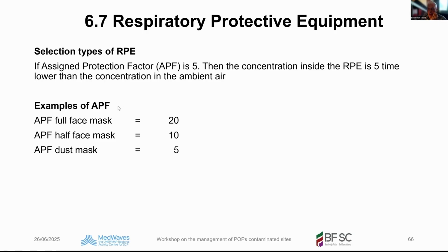When you enter your sites with small vehicles, I told you that you have to use the zoning. In the picture of the zoning, you have your decontaminated zone. So you enter through the decontaminated zone into your contaminated zone. And when you go out, you enter the decontaminated zone again, where you do the decontamination, where you clean your wheels and the outside of the vehicle. And then when it's clean, you go out. So the zoning is an important aspect of not taking contaminated parts outside your contaminated zone.